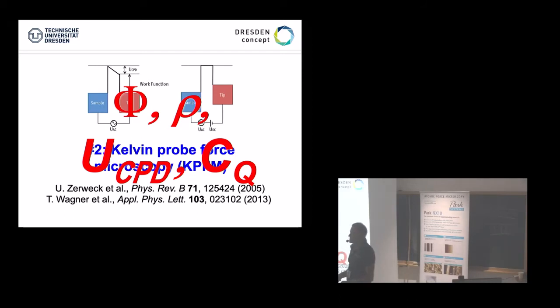And I tell you this is good simply because, as you guys know, I like him very much, but he's a voltage source, right? So when he's a voltage source, he's driving also currents. And if I'm in contact with my cantilever, most of the time I'm charging up my surface unwantedly. So I get also transport properties at the same time when I want to measure. That's why going back with your tip, measuring in non-contact, as we say, is much better, because then you have only that stray field produced by his charges. And that's much, much more elegant. So let me show you how we can do that.